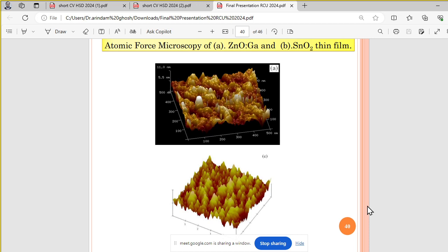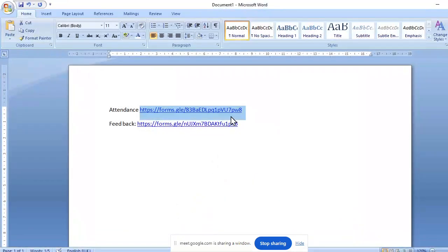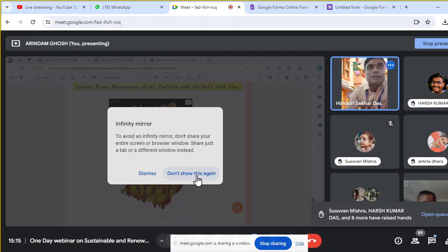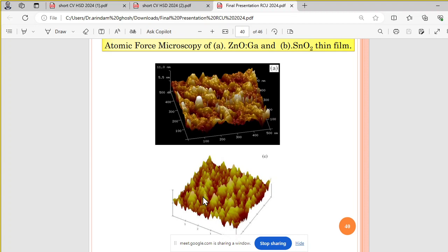The figure shows the surface morphology and roughness of the sputtered gallium doped ZnO and SnO2:F. The surface roughness of the gallium doped ZnO is 8.74 nanometer, whereas fluorine doped tin oxide shows 35 nanometers, which is quite higher comparatively for that application. Surface roughness is also one of the important factors in the performance of OLED.